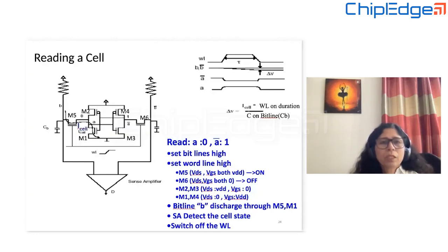But as we have seen in the read, the worst is the ratio between these two. And this PMOS, if we are talking about worst SNM, this PMOS becoming stronger will make the SNM bad, right? These two are both NMOS, so if one becomes slow, the other also becomes slow. That depends upon the technology and the sizing which has been chosen. We have to see.